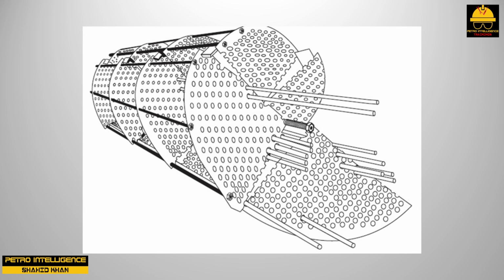The tube support baffles are set at an angle to induce a helical flow pattern on the shell side. The idea is to avoid the dead zones that occur in a conventional vertical tube support baffle. Thus, delta P and fouling are both reduced on the shell side. However, I have 3 reservations.